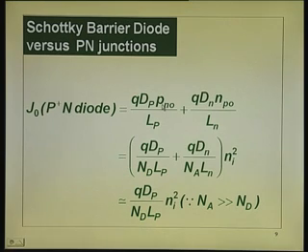And you know that the product of majority and minority carrier is equal to Ni squared. Majority carrier concentration is equal to doping concentration. When you do that, Pn0 is Ni squared divided by doping Nd. Similarly, Np0 is Ni squared divided by doping Na. That is all what we have done there. This is a very standard formula, let me not get into that, because we have discussed it in many forums. So, between these two terms, both will be almost comparable if the doping concentrations are same.